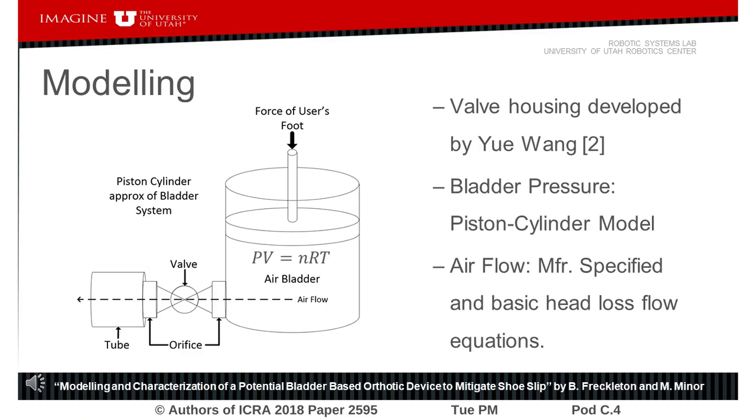Airflow is modeled using a piston cylinder model, air pressure is calculated using the ideal gas law, and flow is calculated numerically using standard head loss equations. This leads to a guide for selecting valves and tubing to create the desired impact upon deflation.